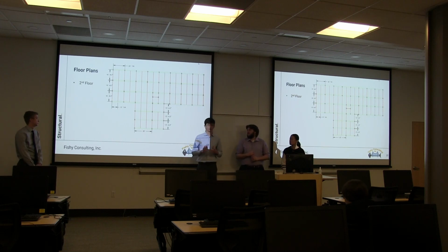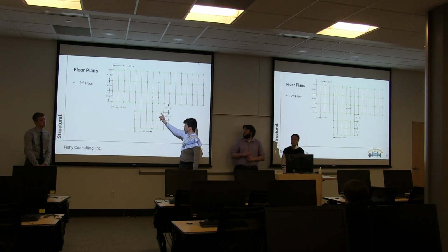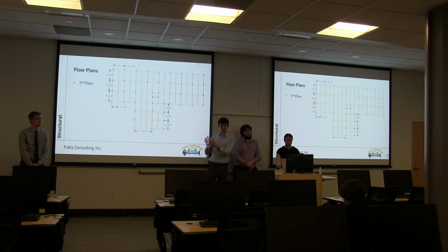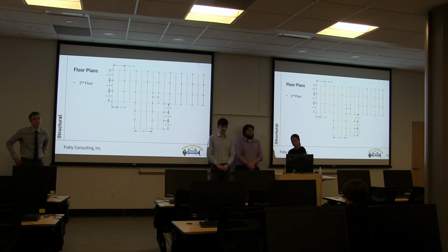The main reason I bring it up is because, for different fireproofing measures, often the stairwell and the elevator are cased in a masonry wall. And you're going to use them as the lateral resisting force system? Yeah, because I may already need them for the stairwell and elevator shaft. They can pretty easily provide a good amount of lateral resistance, so it should be considered.